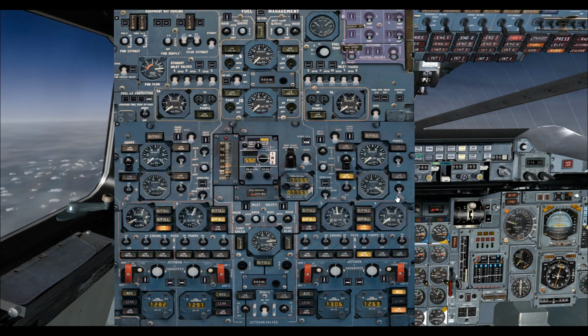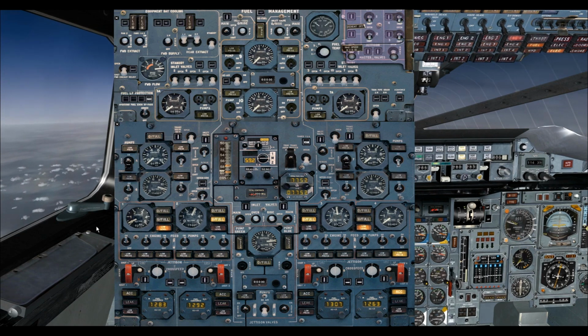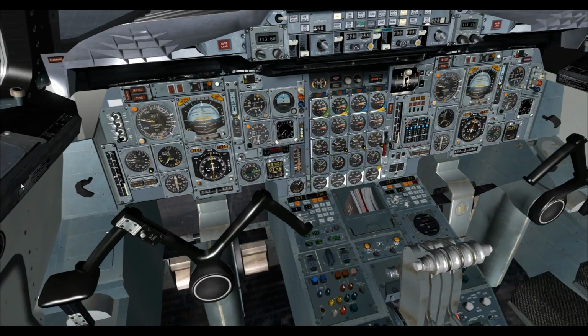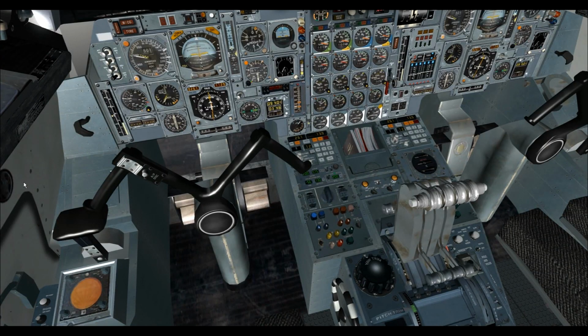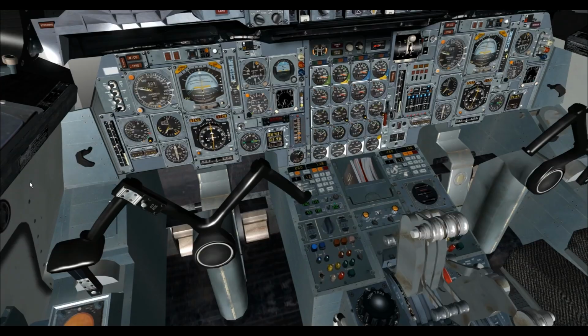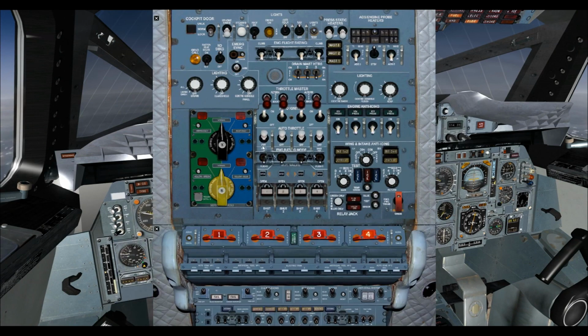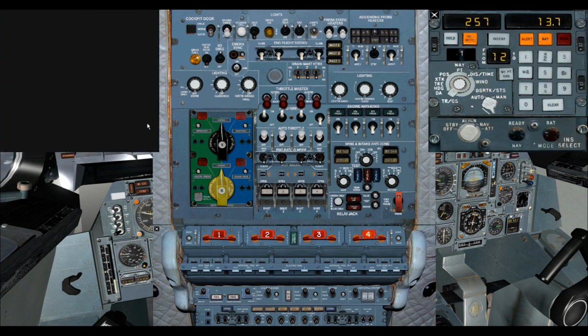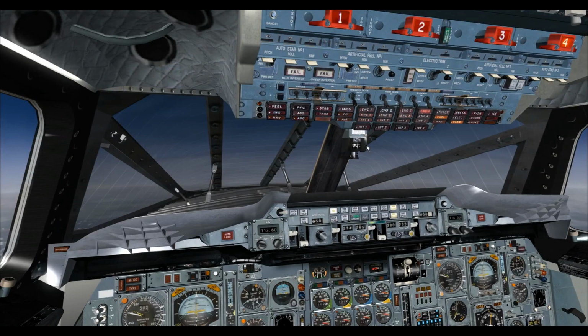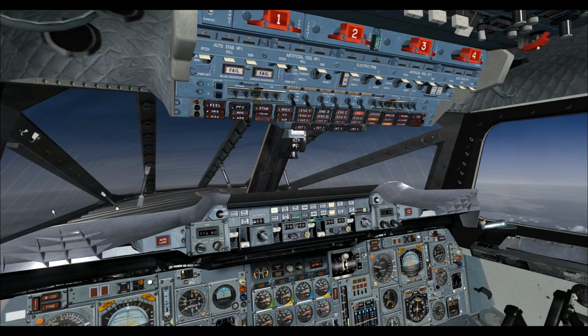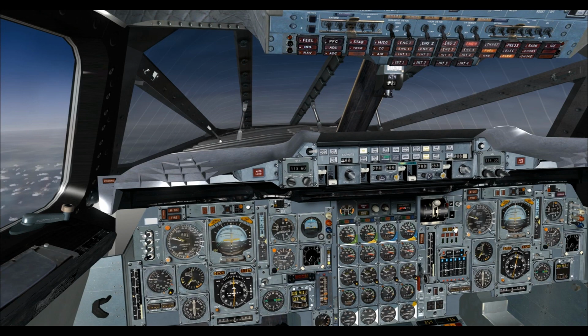So first thing is you have to obviously put the fuel pumps on so the fuel can begin pumping to these engines. The second step is you have to remove the throttle on the affected engine to idle. Step 3 is you need to go onto the overhead panel and turn off the auto ignition, just so it doesn't interfere. And then you want to turn off your HP valve. By the way, just notice that the aircraft handles actually quite nicely on 3 engines, as you would expect. It can comfortably fly on 3 engines.